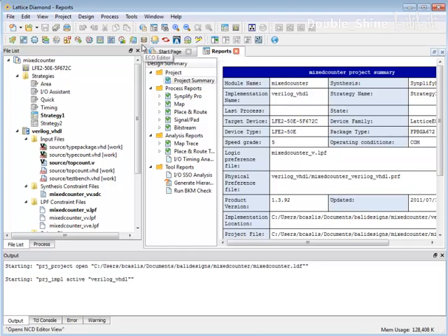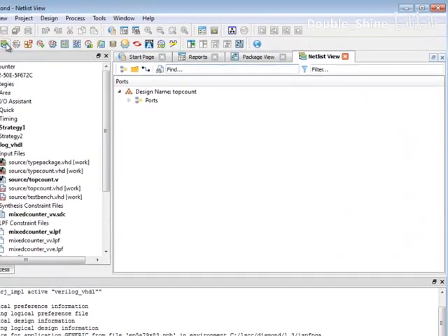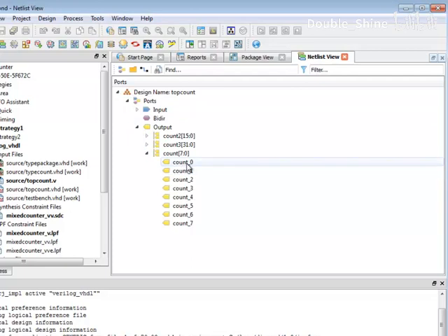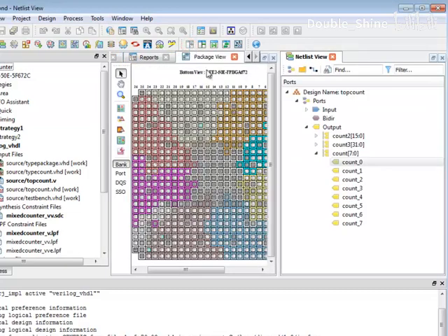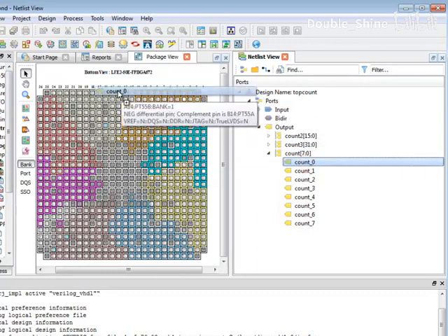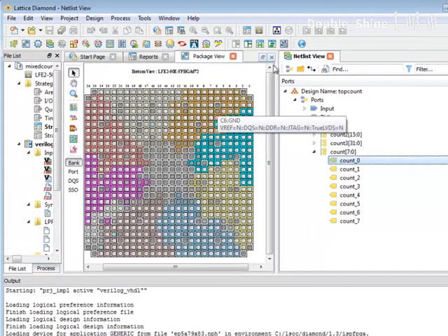So let's open a couple of existing views. Let's open the package view, and then we'll open the netlist view. A common thing I might want to do when using multiple tool views together is, for example, in this netlist view, I might want to drag and drop into the package view. As you saw previously, I can detach tabs, but I can also split this tab group into two independent areas. By doing that, they can expand this, and then I can easily drag and drop from one view to another to do assignments or other functions. So a nice UI capability.